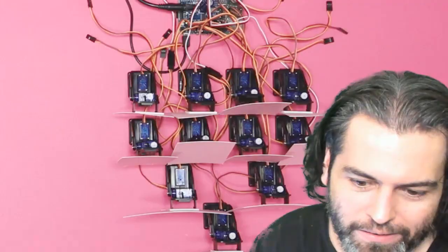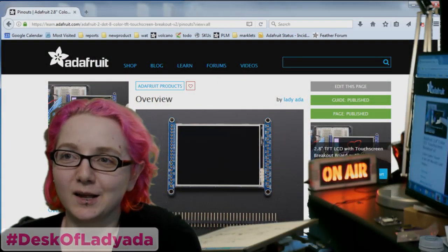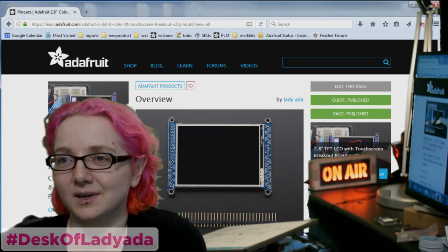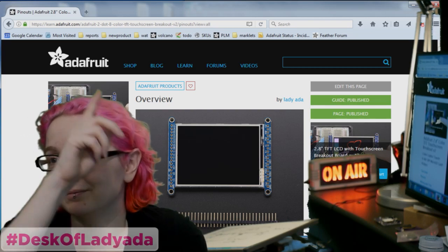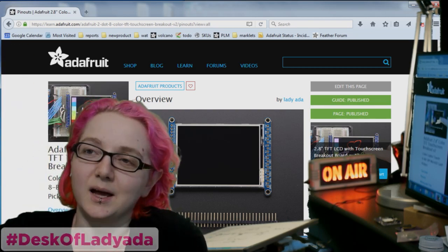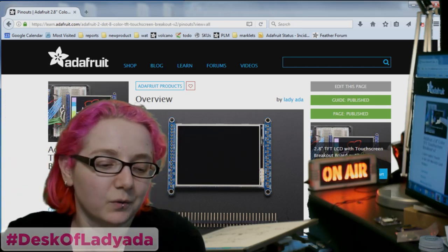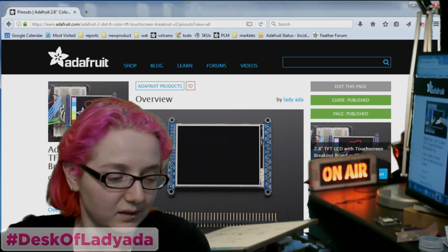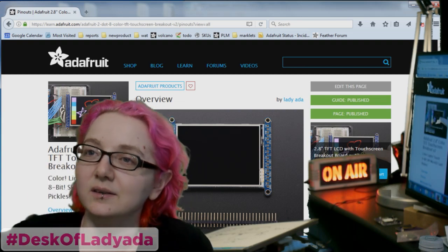Thank you for that wisdom. I hope we learned a lot about resistive touch. Check out the touchscreen library that we have on GitHub. It's under the Adafruit repos, and it's called Touchscreen. You can see the code. It's very simple: pin high, pin low, analog read, swap them. Analog read gives you X and Y values. It works with any touchscreen. We have some example code, and I just updated it today to make it work on all the latest Cortex M0 chips that we are carrying. Good stuff.